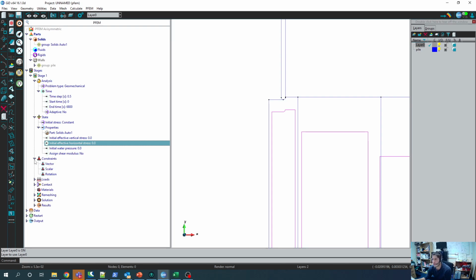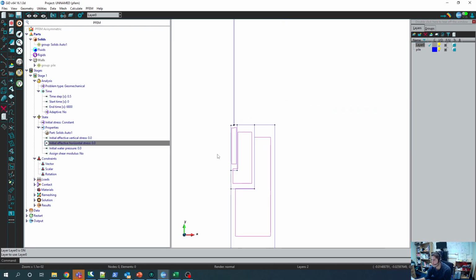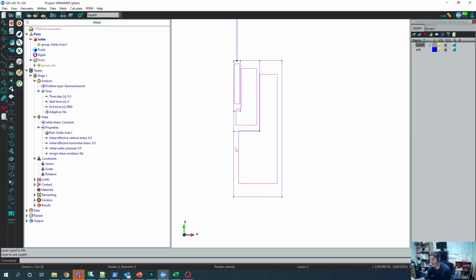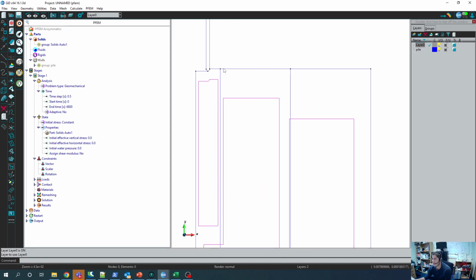Then we have constraints. Let's see what type of constraints. Well, we have to put some boundary conditions on our model. So we will fix this boundary here, that boundary, and those boundaries, whereas this will be free. Now, also for Alvarez's problem, he had some sort of plate on top here that would not allow the displacements up here.